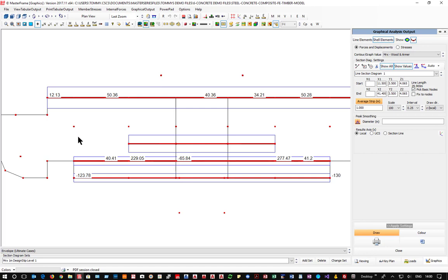Now you'll notice that we actually take the strip past the edge of the member. That doesn't matter. Even though that's 2 meters wide and only 1 meter of it is concrete, it will turn around and say, well, actually, I'll base it just on that 1 meter. So we're not over or under egging the results. We're actually still giving you the correct answers.